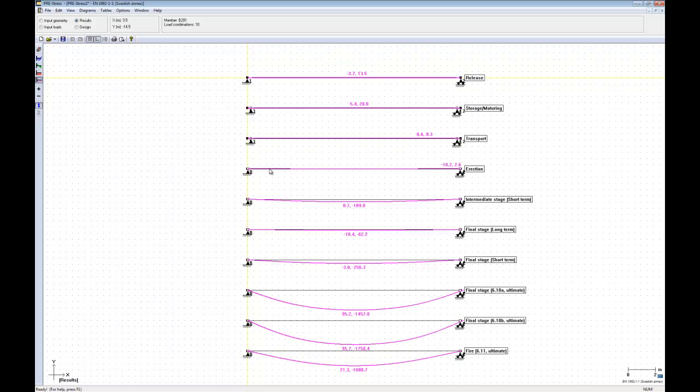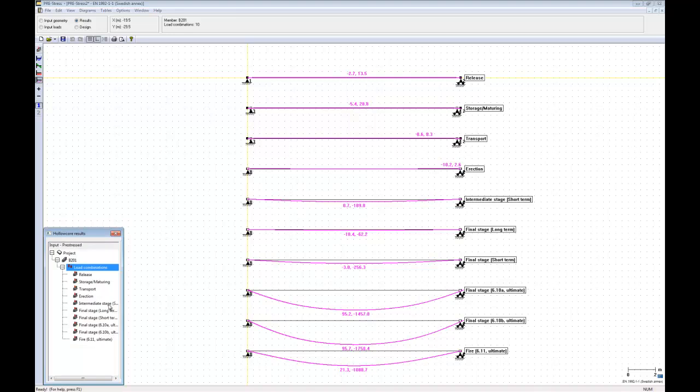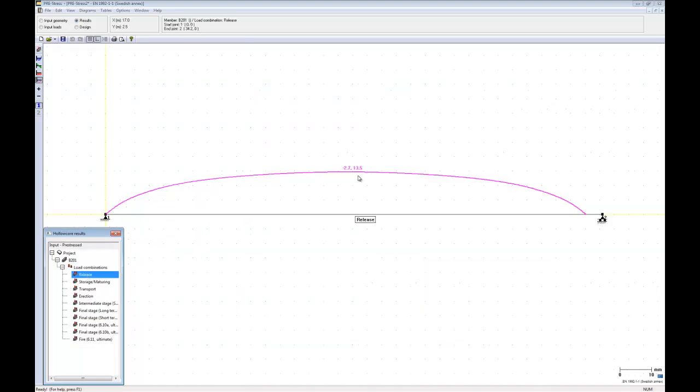And we have the deflection, and we can see that we have two values here. We have the x and the y value. The y value, if we zoom in on the one case here, this is the camber in this case, or negative deflection, while this minus 2.7 is that the beam has been shortened 2.7 millimeters here in the notch, and the total value here in the end will be 5.4 millimeters that this support has been moving inwards here.